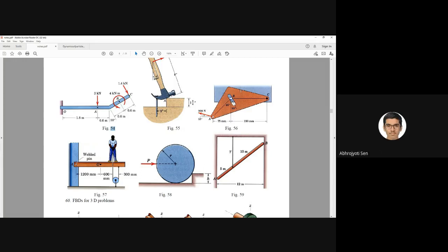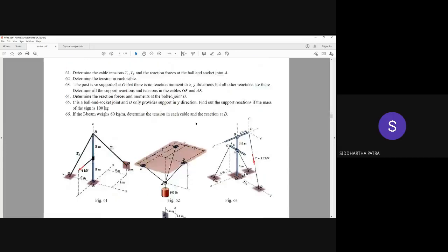So we have to show these moments, just like we show that couple moment through a circular arrow. We have to show that there is a moment due to point A and point C in the FBD. In the FBD, every external force or moment should be there. In addition, there should be the reaction forces and moments coming from the support, while the support itself should not be there. So that I did. Okay, so I hope I made myself clear there.